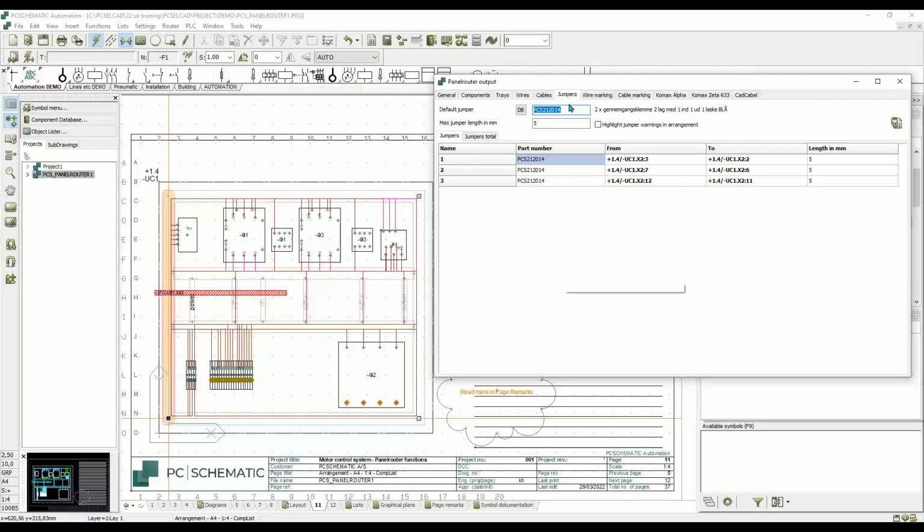And default jumpers, once again, all the jumpers that I used in the diagrams. And then again, if they didn't fit with the length that I had put up in my database, I would get a warning. So you saw that they were routed here, and now I changed it before I got the warning. But if I had the other one, I'd get a warning because it would simply be much longer than it is in the database. So now all the wires are routed in here.